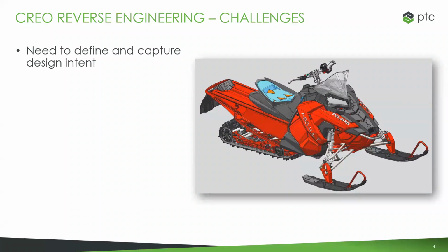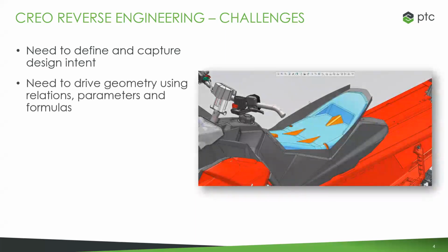All you really have is just a bunch of points floating in a coordinate system, not something that's really usable geometry per se, but you need to be able to make use of that data. And what you really need to be able to do is drive that geometry using math, relations, formulas, things that allow us to have more parametric control over the model. And if you want to make 3D models of your data that you're scanning in, you need to be able to take all that data that you scan and get it into a form that you can actually work with and drive with your dimensions, relations.